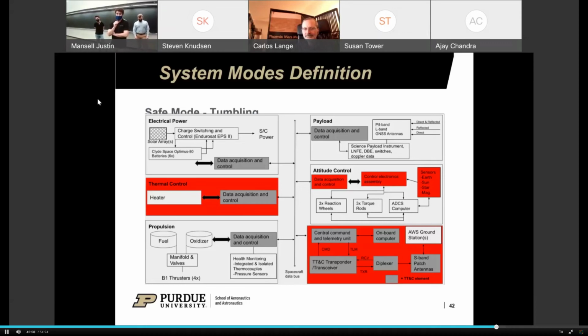Yeah, we do have 3-axis control. Unfortunately, the P-band antenna nominally will be kind of parallel with the velocity vector, so we will have almost no drag in the nominal pointing, but tumbling could definitely produce some pretty interesting dynamics. Thank you for the recommendation. Yeah, that's a good problem for the finite element modeling person. Thanks.